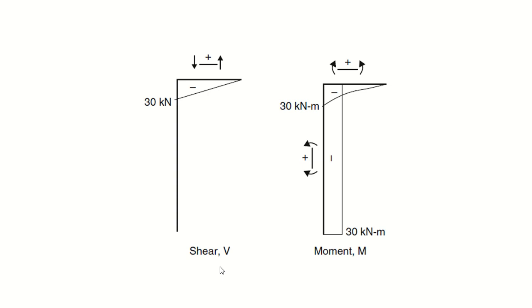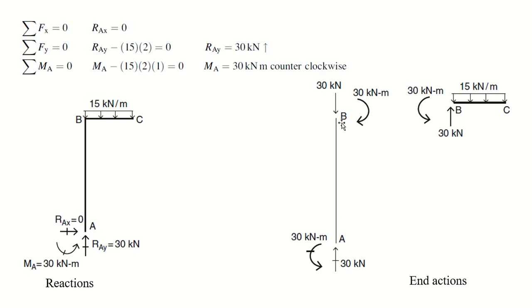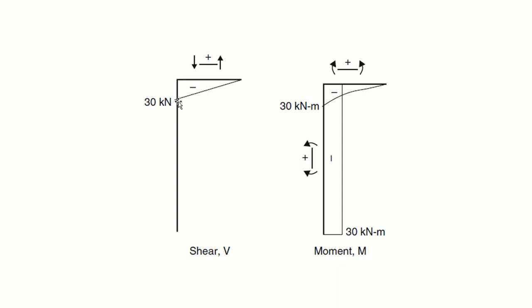So then coming to the shear force and bending moment diagrams, since in the column there was no shear force, there is only axial force and bending moment. But in the beam there is shear force and there is bending moment. So in the beam you have to draw the shear force diagram. This is your shear force diagram. You are starting from this point, the weakest point, coming to the strongest point, and here the reaction is making it 0, right? So from 0 you are coming down to 30, and the 30 force here makes it 0 again.